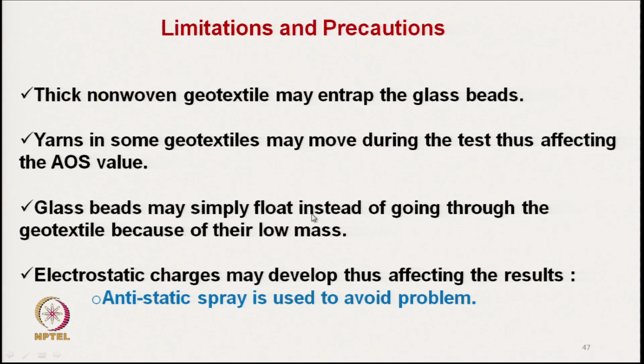The limitation of this method, as I have discussed, is that thick nonwoven fabric we cannot use. If we use woven geotextiles, sometimes yarn may get distorted, that affects the apparent opening size value. Glass beads are sometimes lighter, and they try to float over the geotextile.